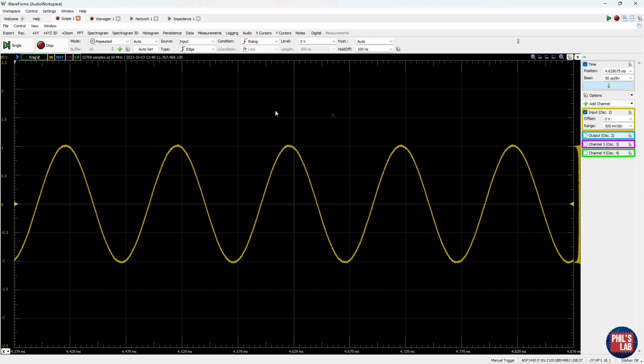So for a 10 kHz input sine wave, which is the yellow trace again, we can see the output in blue, which is the same signal. So for a fairly high frequency input signal, and we'll see what high frequency means later on, we get pretty much the same AC output signal at the output of the RC high-pass filter.